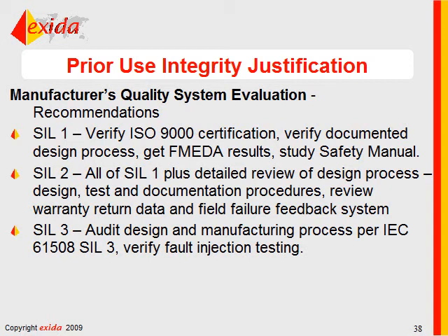Study the safety manual before you buy the product. Get FMEDA results so you can have good, consistent comparisons of failure rates, safe and dangerous failure rates. I would do that as an absolute minimum, even for a SIL 1 justification.